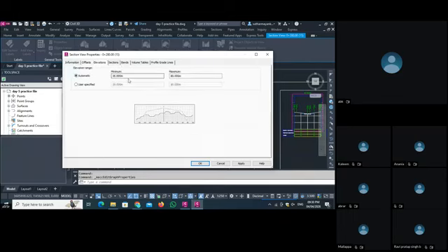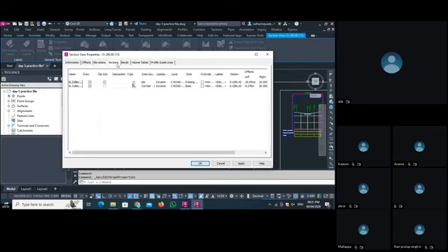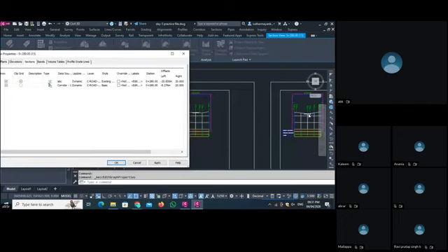The elevation view, if you want to make the elevation more above, you can select the user specified and put the range from here 50 to 100. So the box is automatically adjusted as per your elevation style. The section view style what we provided here, the ground surface and the corridor. So you see the two things here, the ground surface white line and the corridor.